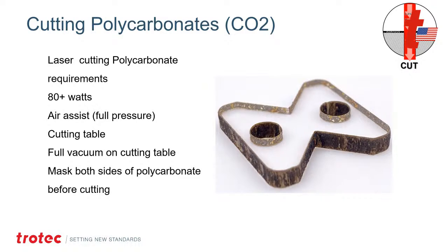It kind of breaks away this carbon material, but it is not pretty. And when you get intricate little inside cuts, it's always going to look like that. Now, if these are screw holes that are going to be covered up, or if the edges aren't going to be seen, again, the tolerance and quality still cuts out beautifully. Just if you're going to see that edge in any way, shape, or form, then CO2 may not be the best process for this. I do recommend at least 80 watts or more.